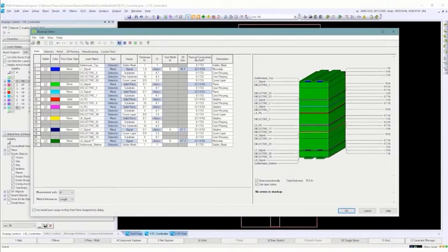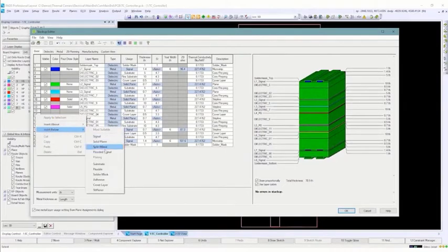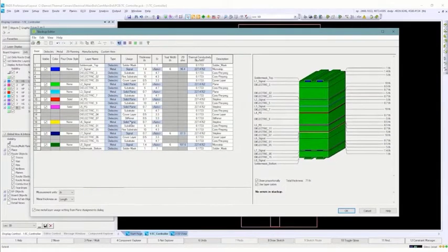So we need to add a stiffener layer because most flex connectors have to have a certain thickness. And as we know, flex material is very thin. You can range the flex material Kapton from 1/2 mil actually all the way up to 9. But it depends on the flex connector that you're using. So in most cases, they do require a stiffener on there. In this case, we're going to route the traces on layer 7. So the stiffener is going to end up being just above the cover layer on layer 6. So above here, we'll add a stiffener for both of those. We don't need one for our button board because obviously it's going from one board into another board.